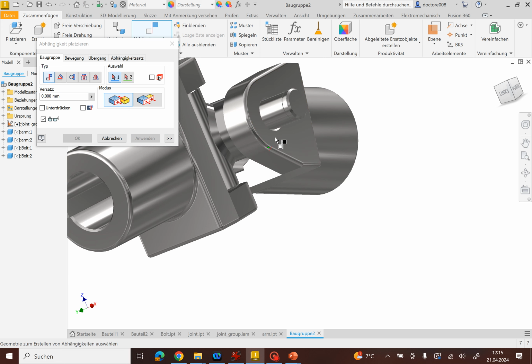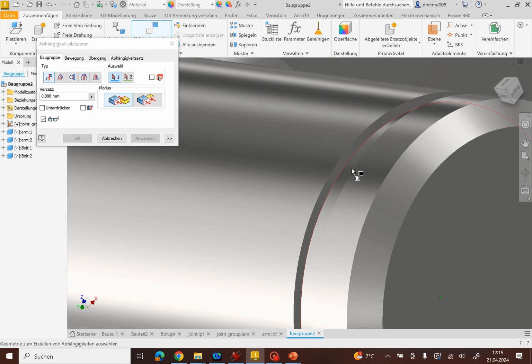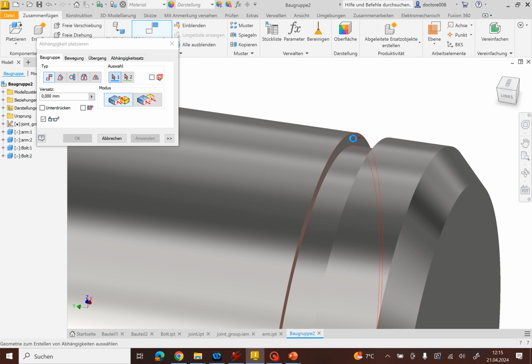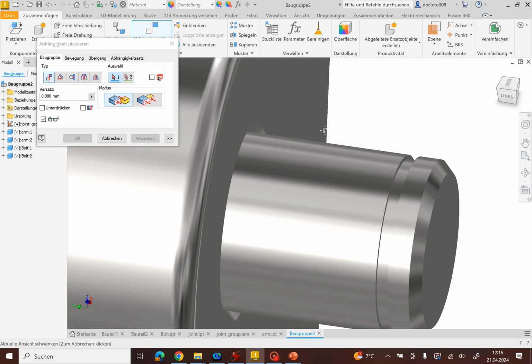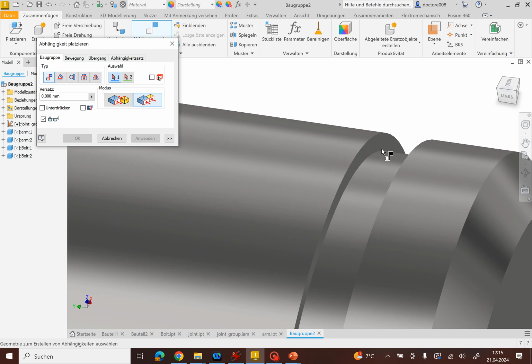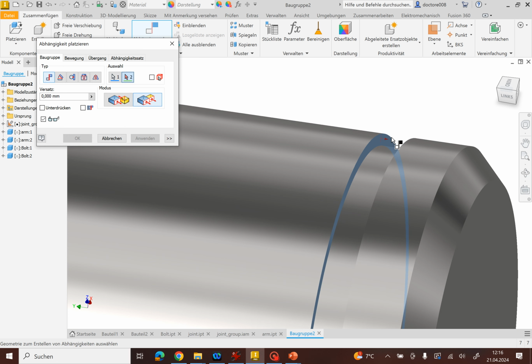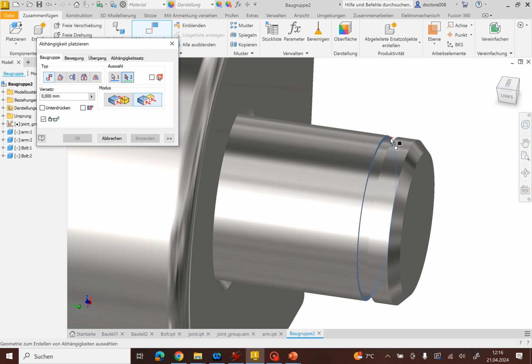Now it's a little bit complicated, because you remember this small nut on the bolt over here, this one. And this area needs to be in the same direction as this area. So listen carefully. We need to switch to that button. Yeah, click on that button. Zoom in and make sure that you select this geometry of the bolt, which turns blue now. And click on that geometry.